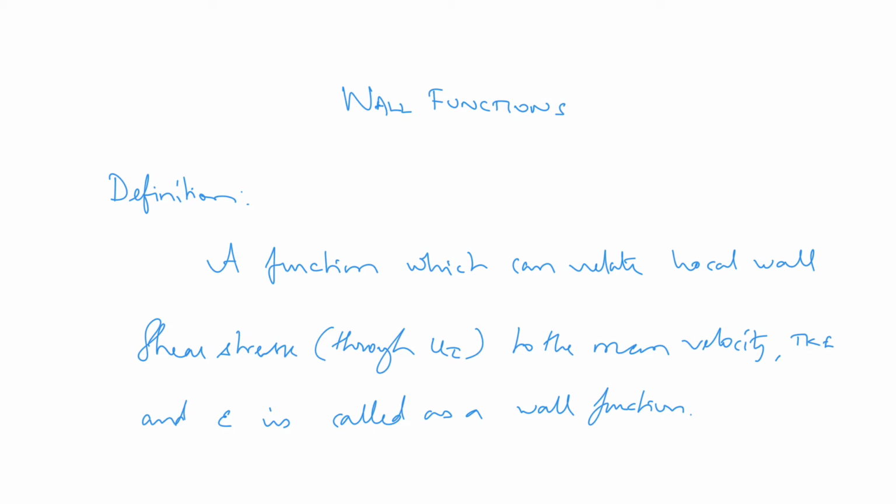In this lecture, we will discuss wall functions. A function which can relate the local wall shear stress through the shear stress based velocity to the mean velocity, turbulent kinetic energy and dissipation of turbulent kinetic energy is called a wall function.